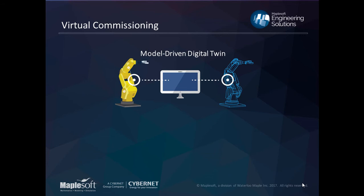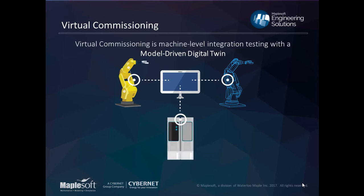And some digital twins are created in a big data sense. And what that means is the product is shipped, and we use a lot of sensor data to provide a model. But from our perspective for virtual commissioning, we use a model-driven digital twin. So this comes first. We've got this model, and then we are enabling the virtual commissioning process, which is machine-level integration testing using this model-driven digital twin.